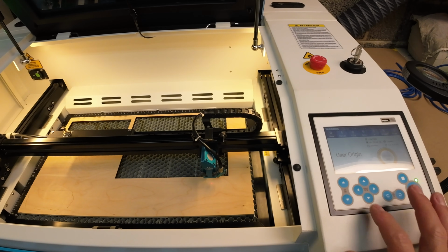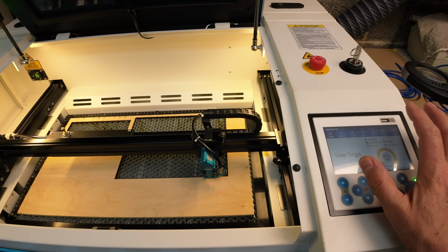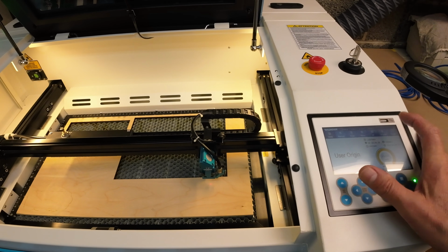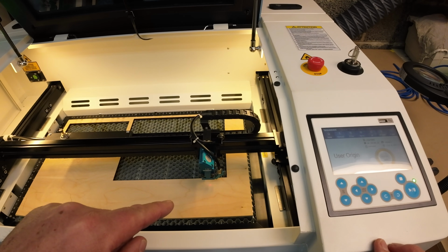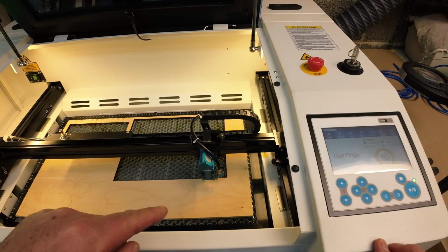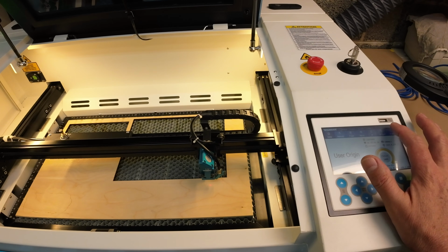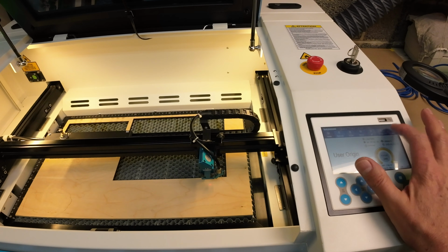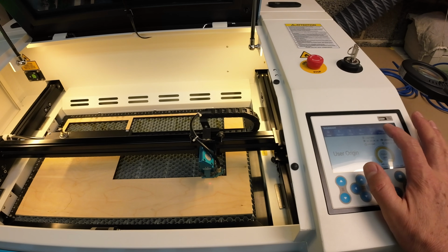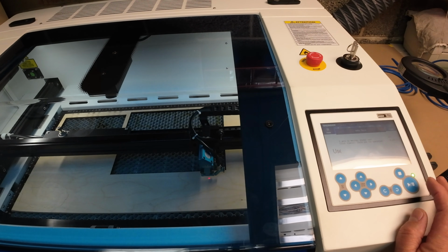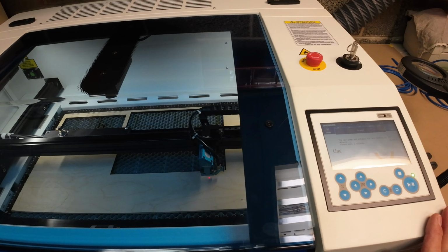And I think, okay, I've got about 3 inches there. I come up here and I press the origin button, and that tells the bolt that this is where the green dot is in my design. And I'm going to frame it, so I frame the design just to make sure. Yep, got lots of room. I've got my origin set. That's when I autofocus and I press start, and away we go.